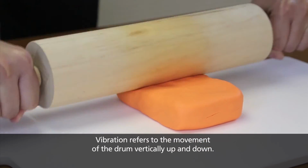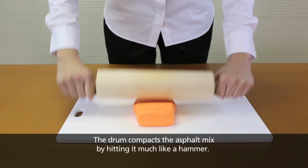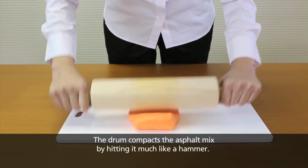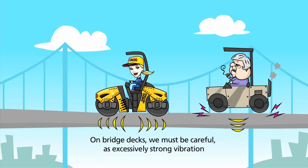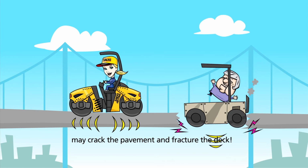Vibration refers to the movement of the drum vertically up and down. The drum compacts the asphalt mix by hitting it much like a hammer. On bridge decks, we must be careful, as excessively strong vibration may crack the pavement and fracture the deck.